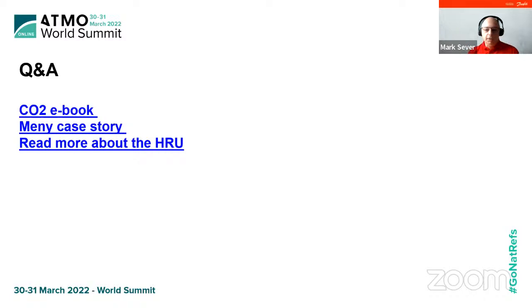The controller on the heat recovery unit will again send a heat recovery request to some other PEC controller, which will manage to increase the pressure, probably, because all other refrigerants are not going into this transcritical area. So based on this heat recovery request, you can tune your pressure in your refrigeration system. Is it ammonia? Is it some other synthetic refrigerants? In principle, you can use it also for other refrigerants. So yes.